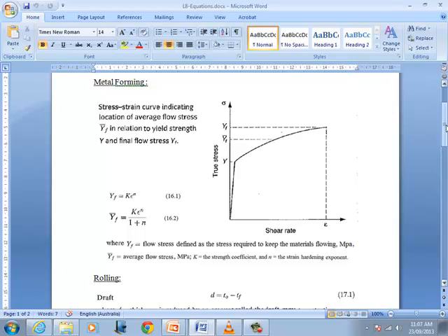We've got the raw material, okay? The raw material. Its hardness is something. We subject it to deformation, say for example rolling, and we take something out. This material is now harder than the original material, isn't it? It is. You subject the same material to another deformation process, another rolling pass. Again, it becomes harder and harder and harder, depending on the magnitude of the work hardening or deformation.